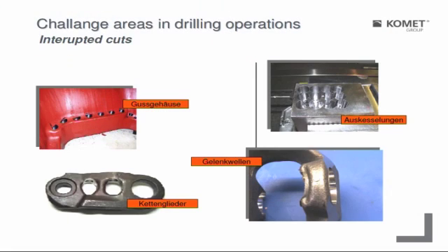What will be another challenge in drilling with indexable insert drills? This is definitely interrupted cuts. Interrupted cuts destroy all that we do when we are balancing the cutting forces, when we try to achieve a cylindrical hole. An interrupted cut means that the tool is cutting only with the inner or with the outer insert. So we need a lot of rigidity, but look at a 5D drill doing an interrupted cut, just drilling a half hole, a half pipe bore.